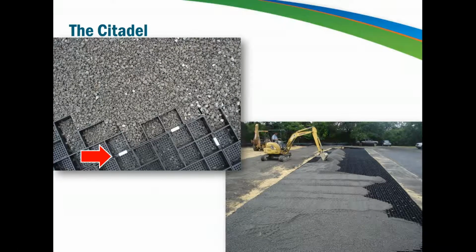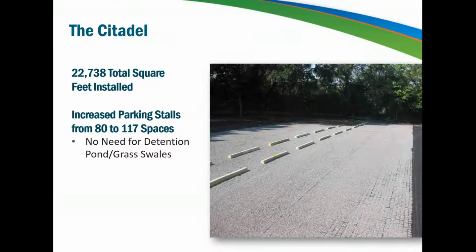So the U-clip connectors are easy to install, and it's really apparent where they need to be placed. Some of the walls are half height, and those half height walls line up between paver units, so the contractors know exactly where the clips are needed. The clips can be installed with a single worker without needing electrical equipment. A small excavator or front-end loader is a great option for placing the stone infill.